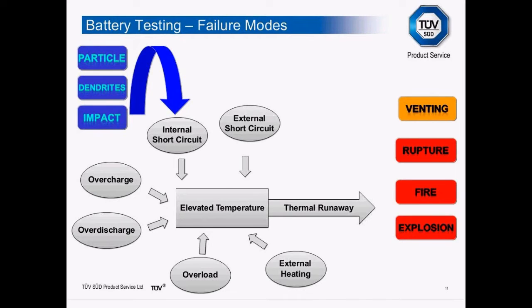Also, other manufacturing defects such as poor electrode alignment or cell tab insulation, if not correct, also cause short circuits. Dendrites, which are metal fibres that form on the carbon anodes, are caused by poor fast charging or discharging, so basically excessive charging above the limits, and this has the potential to compromise the separator material.